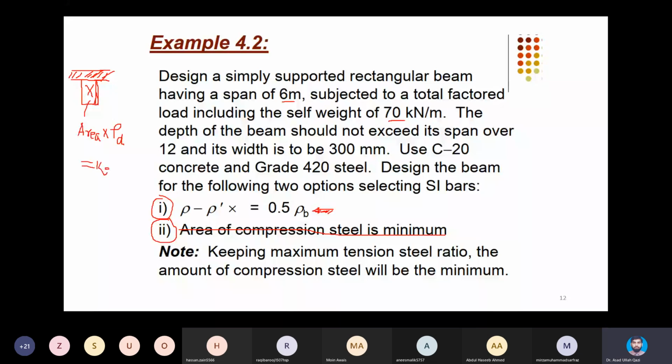I can multiply this with 9.81 divided by 1000 to get the self weight of the beam in kilonewton per meter. Then I can multiply it with 1.2 to factor this self weight, and I can calculate the ultimate self weight of the beam. That will also be added in the beam line load, which we earlier calculated based on the slab load, or if there is some wall directly constructed along the stem of the beam, that will also be included. So don't forget, not only slab load, self weight, floor finish loads, wall loads, the stem load of the beam also needs to be considered.